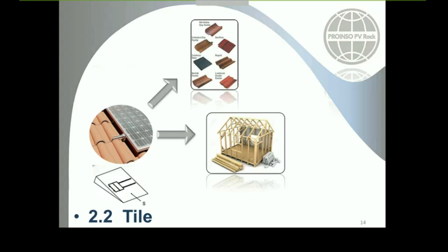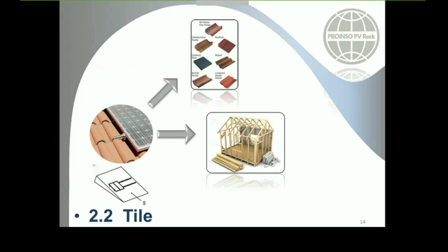These tile pieces are made of steel because they support more loads. Aluminium for this kind of load transfer could sometimes be risky for the tile version of the kits, and I think all of the solutions in the market for tile are steel ones. In the case of the tile, as we can support more loads per fixing, I think we are using 4 in each rail, so 8 in total. This is always linked to the loads that we will have.